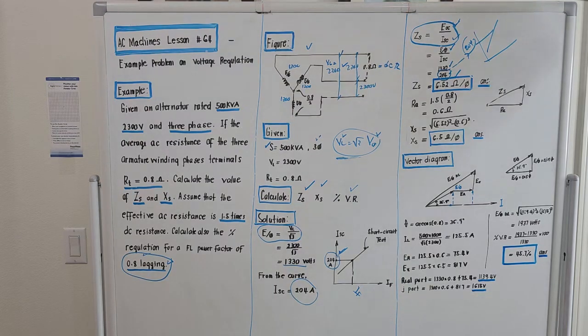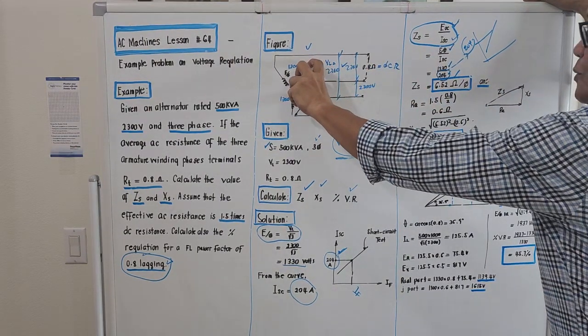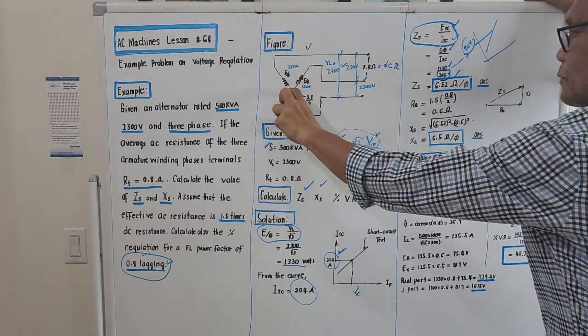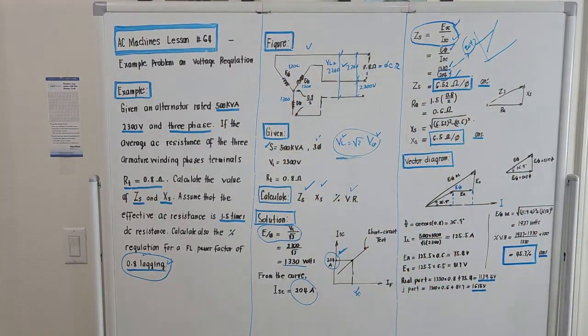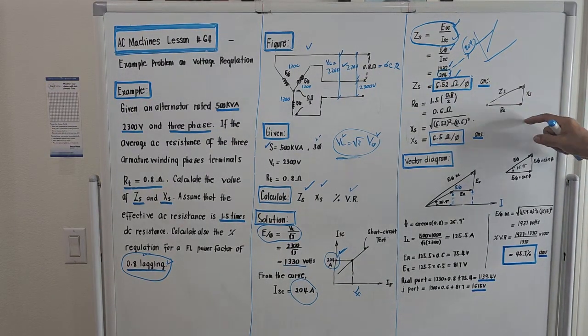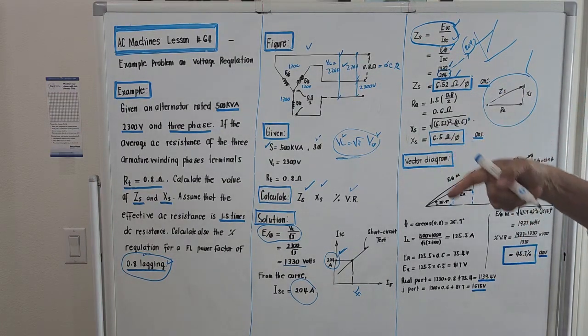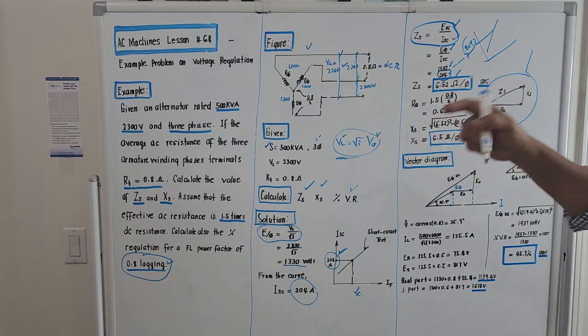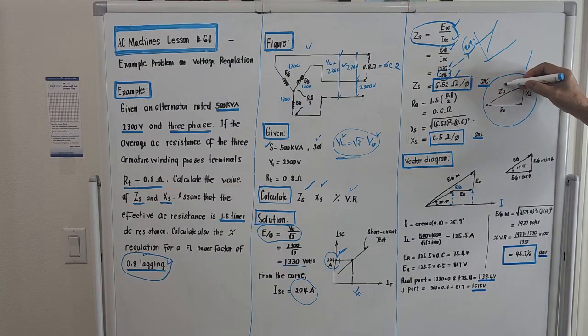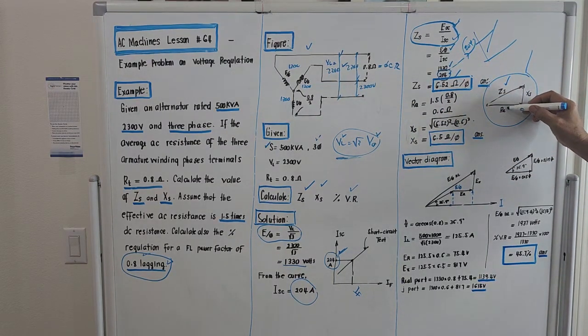Meaning the synchronous impedance per phase is 6.52. Synchronous impedance is a vectorial addition of reactance and armature resistance. So this is actually the total. It seems we are now on AC circuit, right? Like what I said before, our knowledge under AC circuit will be applicable to transformer and alternator. That is, the impedance is actually the vectorial sum of the resistance plus the imaginary part, jX_S.